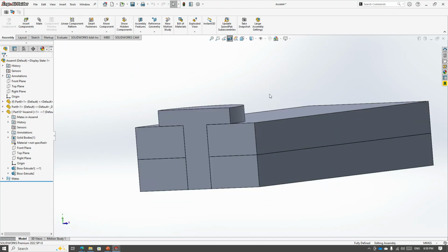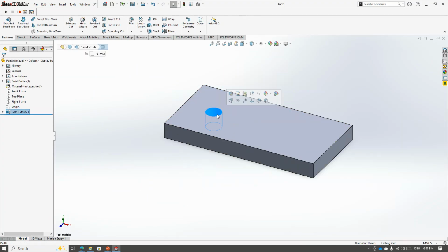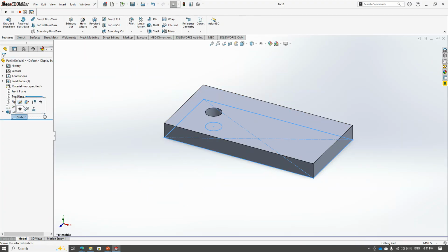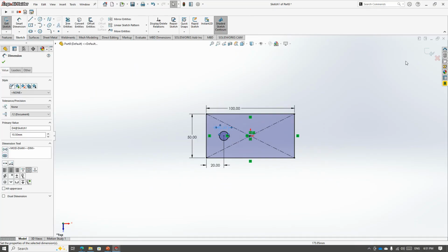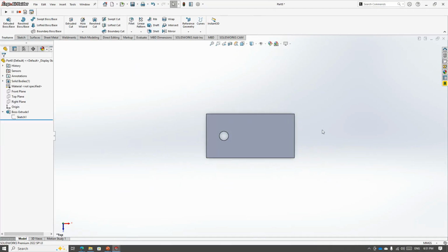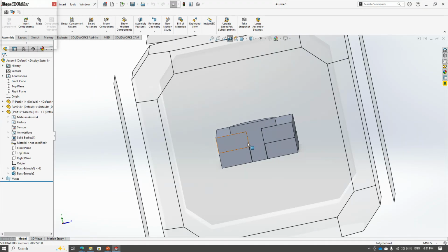what you can do is go to the main part and change the diameter from here to 10 mm. I want to get the offset, maybe the tolerance, maybe the clearance of 0.5 mm. I will just specify 0.5 mm addition to make it a little bit bigger, so that we have the clearance between those parts. When I save it, you will see.